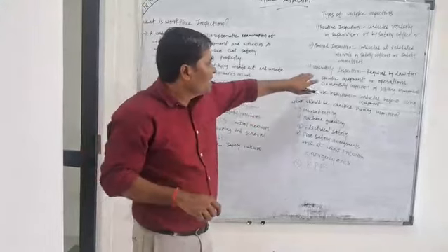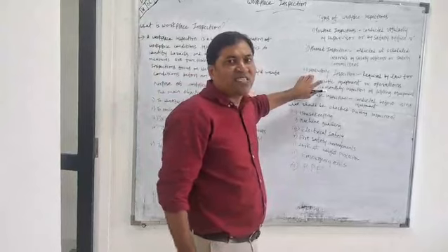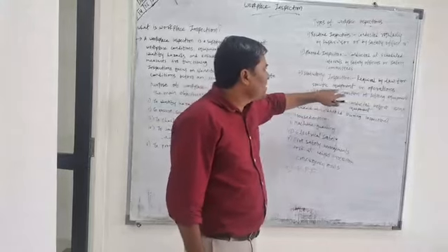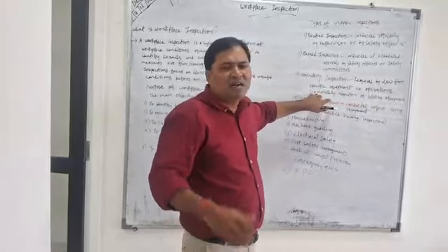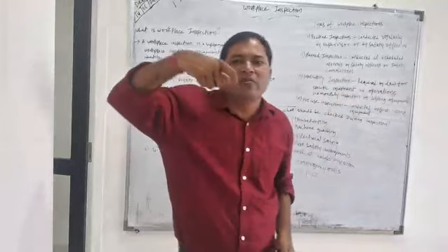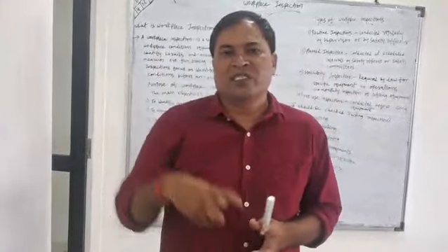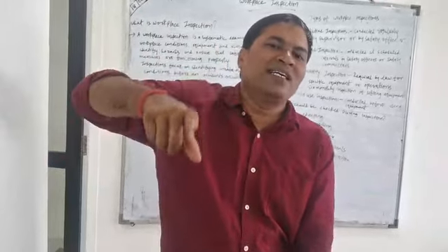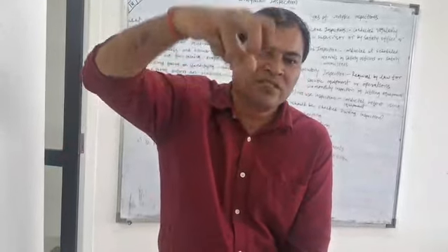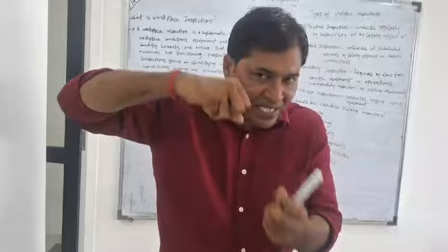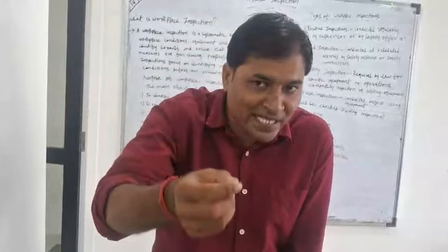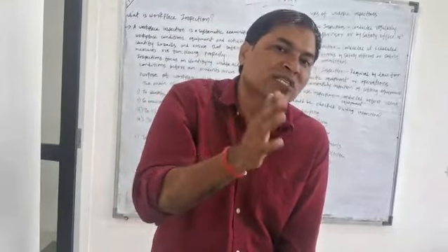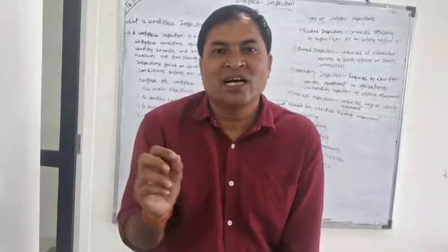Understood? Then you have to go with the statutory inspections, which are required by the law. Okay, like required by law for specific equipment or operations, like within 6 months. If you are going with the crane operations, checking of the crane operation equipment, lifting operation, lifting equipment regulations. So that requires every 6 months you need to check the weight capacity, the lifting capacity of the belts, the lifting capacity of the slings, the lifting capacity of the wires, whatever equipment is being used in the crane, okay, that is required by the law.